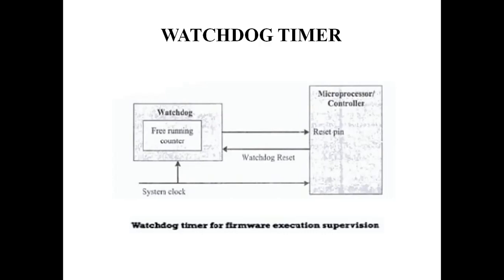If the processor or controller doesn't contain a built-in watchdog timer, the same can be implemented using an external watchdog. This is the external watchdog timer IC. The external watchdog timer uses hardware logic for enabling and disabling. Resetting the watchdog count is done using a watchdog timer which is built externally. This is what the watchdog timer is.